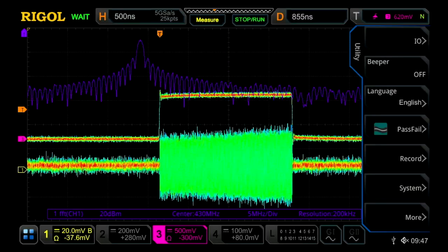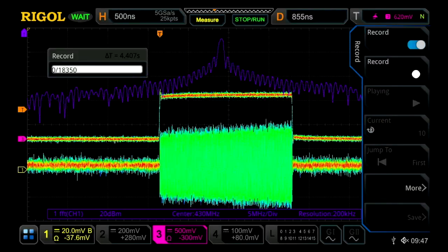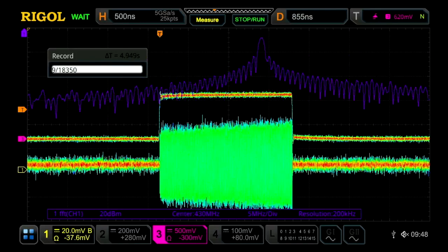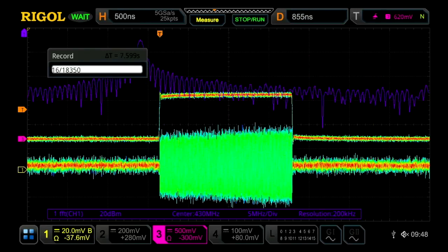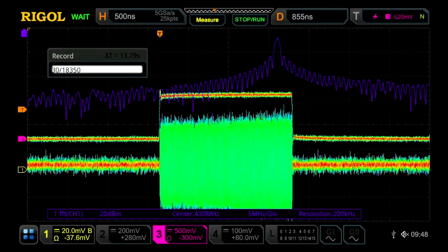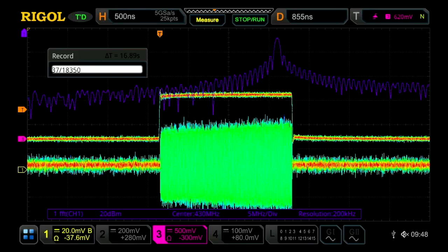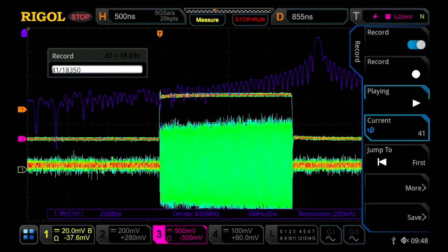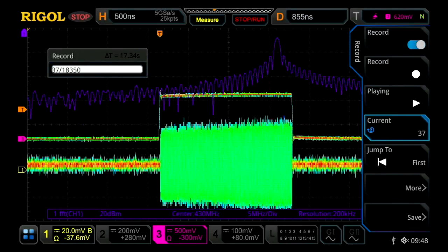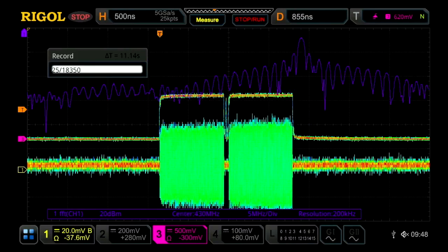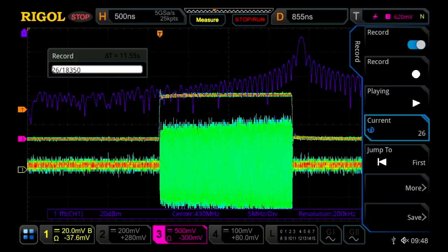Well, one way is we can use the record mode capabilities within this scope. And this will let you record really thousands of frames of activity. So each pulse that is triggered causes a frame. We're capturing those frames and really using the sequenced and segmented memory here to do further analysis. Whenever we feel like we have enough, we can go ahead and stop that activity. And then we can play it back either as a movie, or we can look through sequences of frames, and we can go and look at each bad pulse or double pulse: what's causing that activity, what frequency is that at, what's the pulse sequence and timing, and see how that all works together.